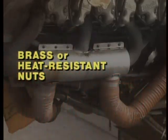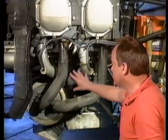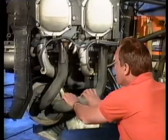Brass or heat-resistant nuts. Also, you know, there's a lot of expansion and contraction in an exhaust system because it heats up or cools down. So you have slip joints installed very often, and they're required in most exhaust collector systems because of expansion and contracting caused by high heat and cooling. So very often you'll have slip joints. What's the purpose of a slip joint in an exhaust collector ring? Well, it aids in alignment and absorbs expansion. That makes a lot of sense.